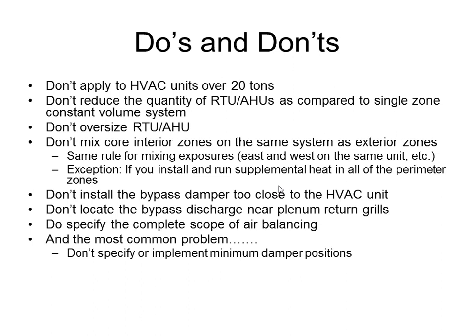Another don't is mixing interior and exterior zones. I know the conceptual layout we showed you did do this, and that was okay because we had supplemental heat. But if you do VVT zoning where you have a west exposure, an east exposure, and a central exposure, and you don't have any supplemental heat, you're going to be fighting the whole time. The whole day you're going to be calling for either cooling or heating when one zone is only requiring heating and the other zone's calling for cooling. So you want to make sure that your zones have similar types of loads so that you can control properly.